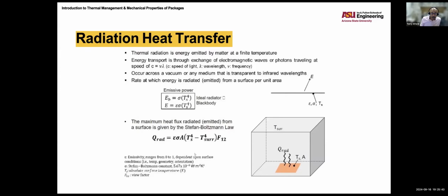So I can get heat conducted through the board, and through the bottom of the package. And if I have a fluid flowing over the die, I get even more convection. And if it's forced convection, even better.